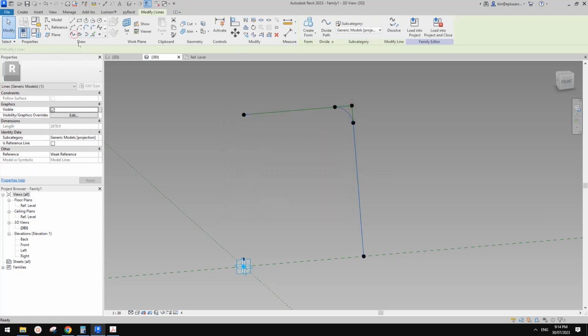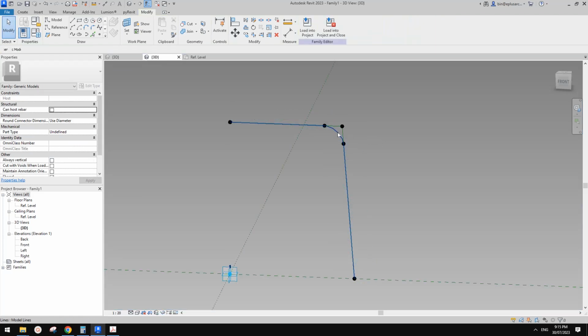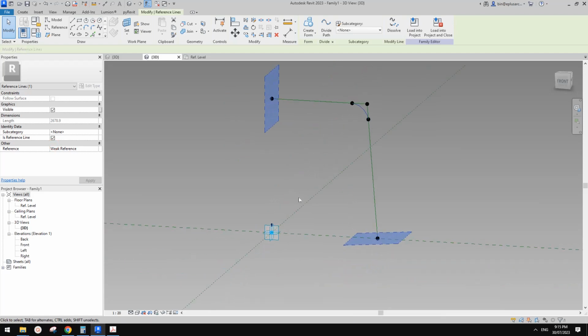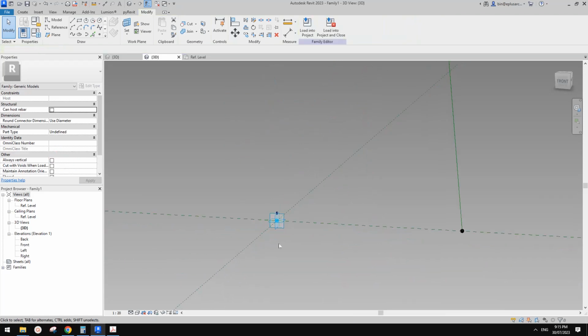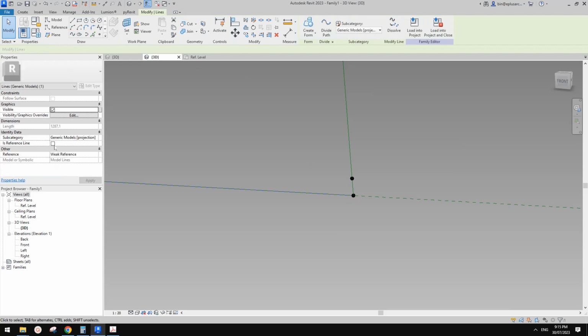Now let's create a spline through them, so you can see this is it. So if I type HI, I select it, so you can see this is a spline with a very straight part here, and then an arc. Okay, so HR, and I'll select this and make it reference line. And okay, and then we just need to close it. Okay, so select this, just make sure to zoom in. So pick this one and create a spline, make it reference line, and do the same.